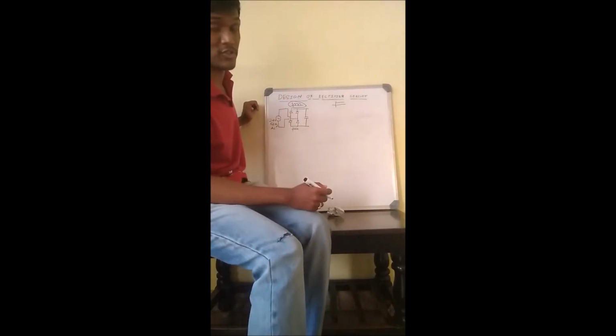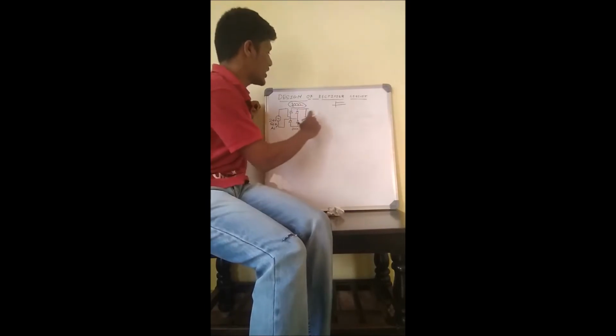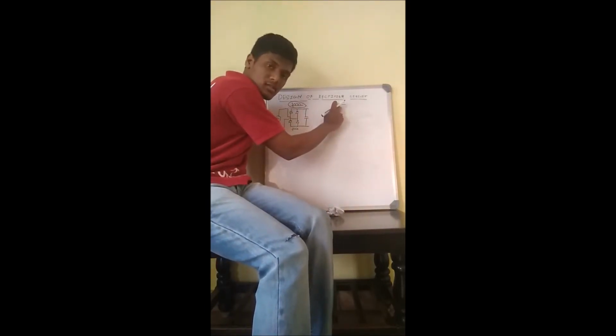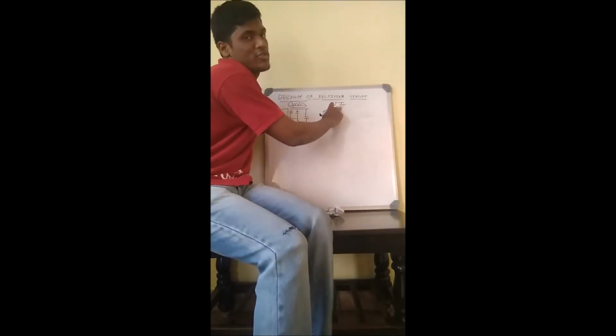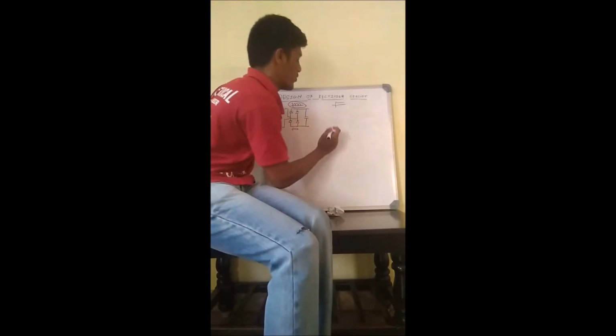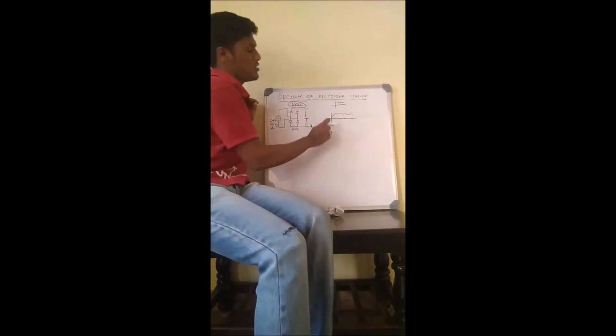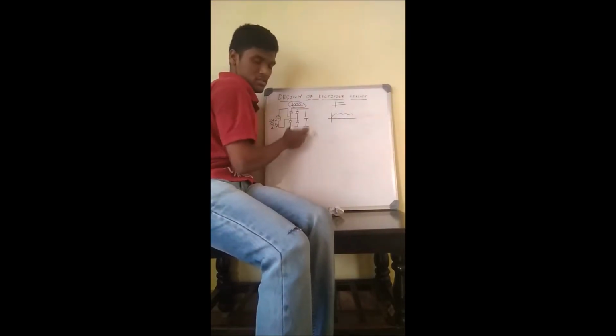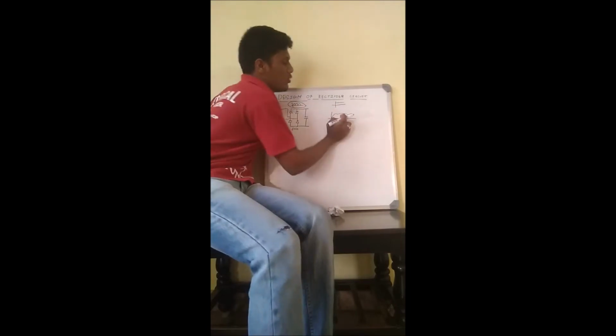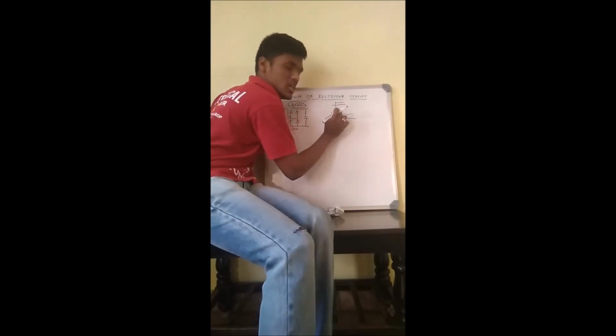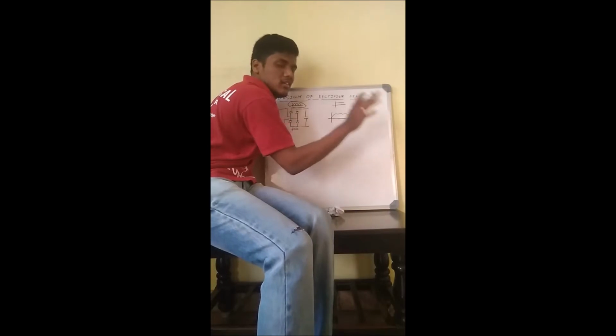So do you think after adding the capacitor, you will get exactly like this? No, practically impossible. So how do we get the waveform? Generally after adding a capacitor in parallel to the circuit, we get a waveform like this, which is almost like a DC.